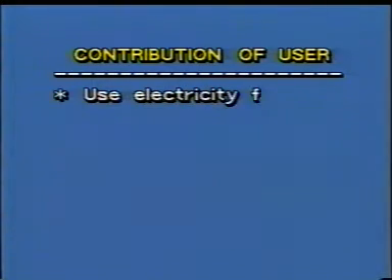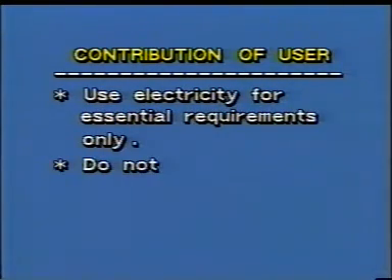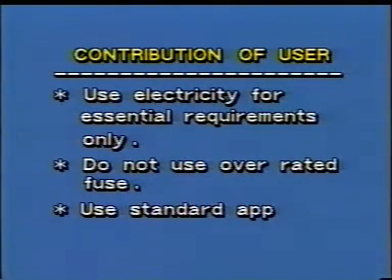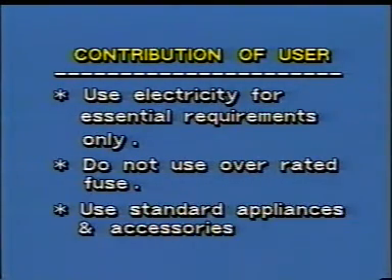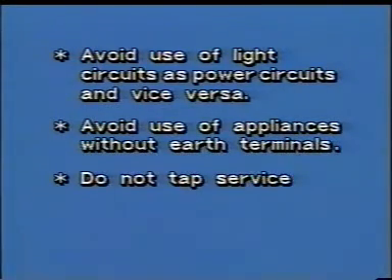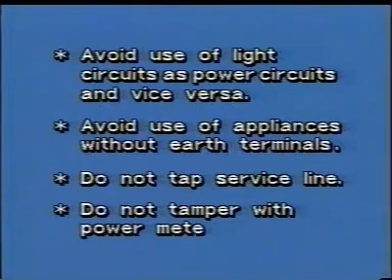Use electricity for essential requirements only. Don't use overrated fuse. Use standard appliances and accessories. Avoid use of light circuits as power circuits and vice versa. Avoid use of appliances without earth terminals. Do not tap service line. Do not tamper with power meter.